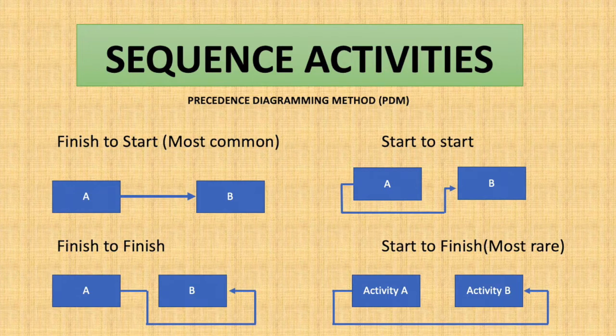Your documentation cannot be completed until you have that letter from the inspection company. So your first activity, the predecessor, documentation, cannot finish until you have that letter from the organization you are waiting for. Then you can submit your documents. So this type of relationship is finish to finish.